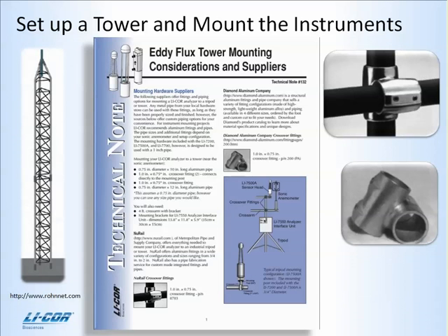We also have a tech note dedicated to the tower and mounting of the instruments. So if you're looking for solutions on what's best for your site, for example, do you want to use a tripod or do you want to use a tower? We discuss the different rail fittings, how to anchor the tower, suggestions for lightning protection, and also give a list of suppliers that might help in answering further questions for your site.